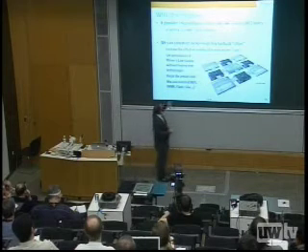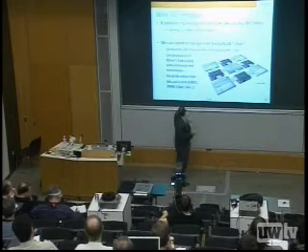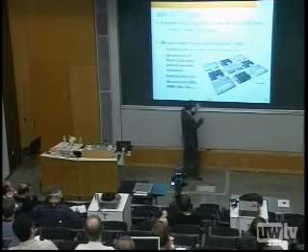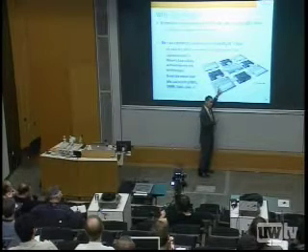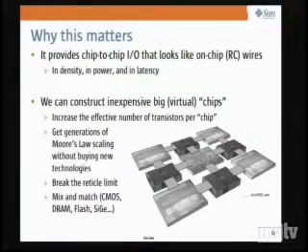Well, if I can have off-chip I/O that looks like on-chip wires, well, then I can imagine, okay, this is just a cartoon done in SketchUp, not a real chip, not a real system, but I can imagine a system made of lots of chips aggregated together with proximity I/O. So imagine I've got processors in the corners, I've got a stack of DRAM over here, maybe in the middle that's a switch of some sort. They're all face up on a cold plate, and then face down I drop these bridge chips.